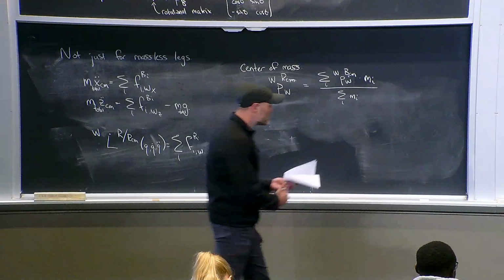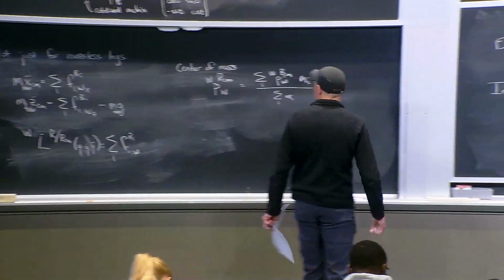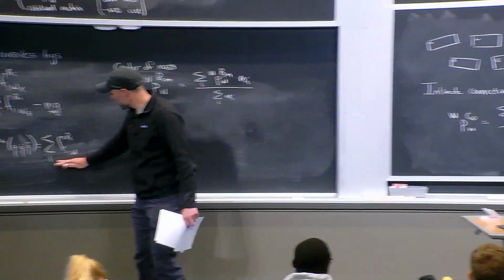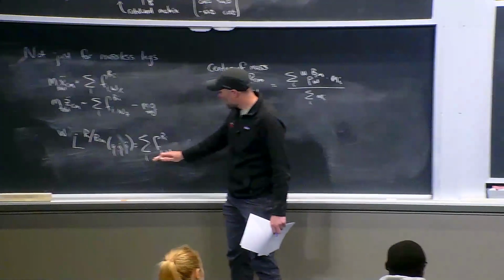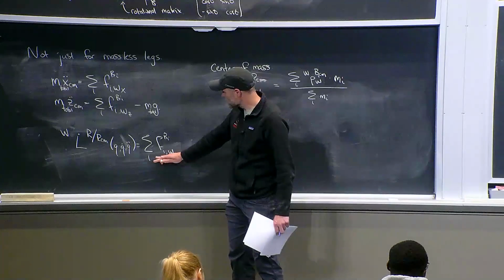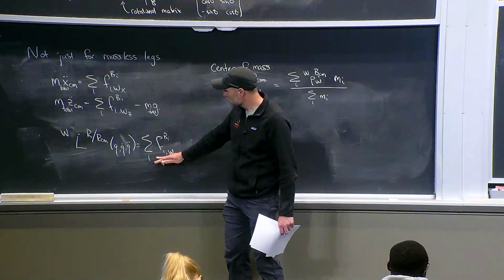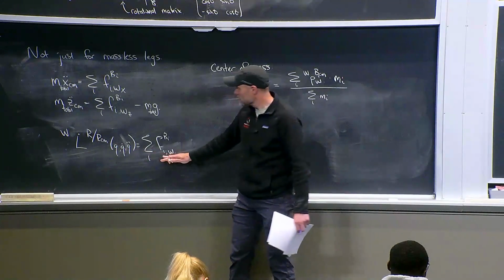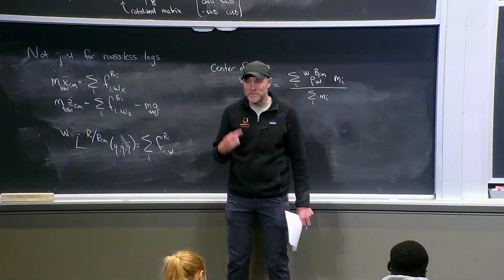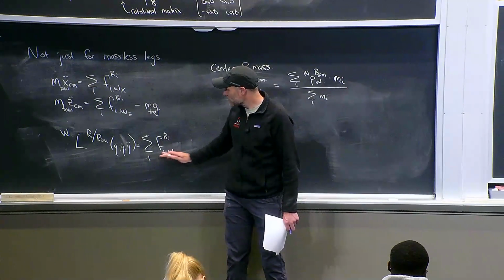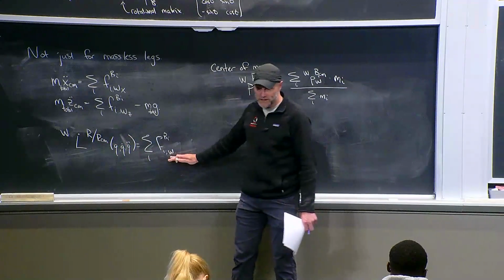And it turns out that if you were to recast these potentially complicated equations with position cross force sitting inside here, and write things in terms of the center of pressure, then actually these equations simplify beautifully, okay?